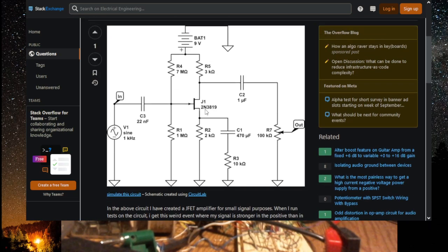So when we set the circuit up and set the calibration signal, we do a sweep to determine what the linearity is of the circuit. And if some signals get amplified at a higher rate, that's why we put in the filters. But I don't know, maybe it's important after that preamp stage or not.